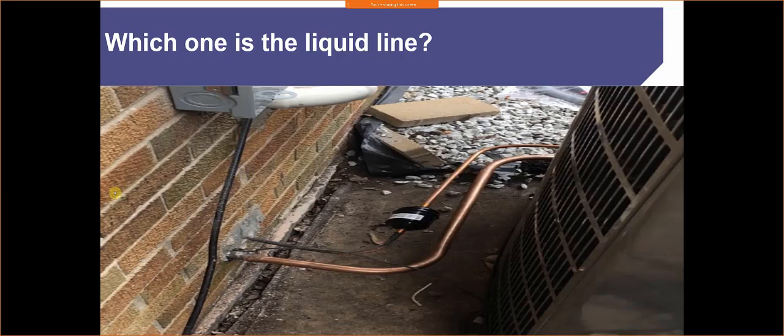Well, our refrigerant is traveling from inside. We've absorbed heat from the evaporator. I don't want to absorb any more heat. Okay, I don't want to absorb any more heat traveling down here, because as I travel further, the pipe's exposed to atmospheric conditions, there's still heat available and the refrigerant is going to still try to absorb it.